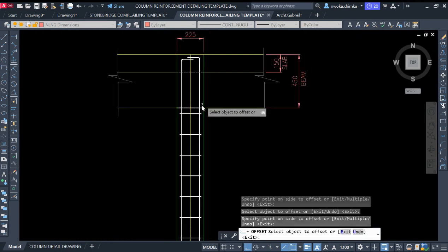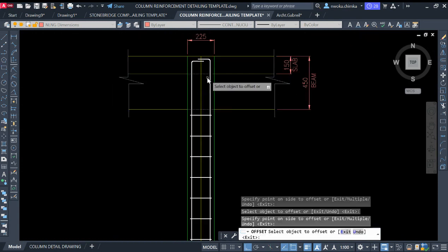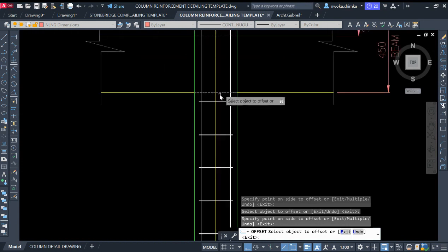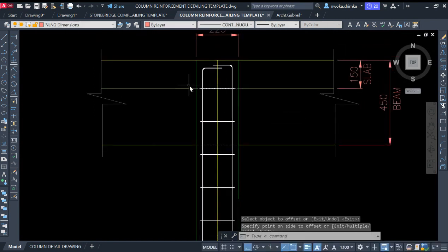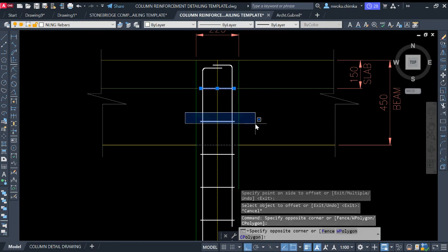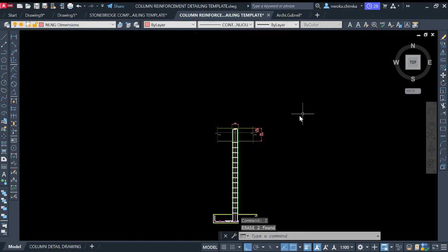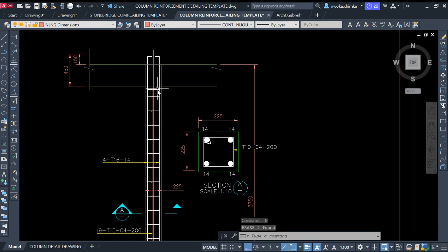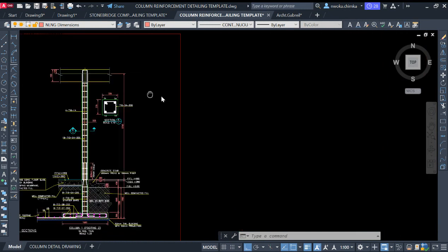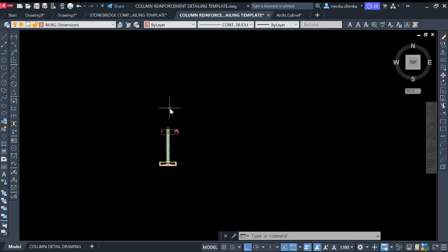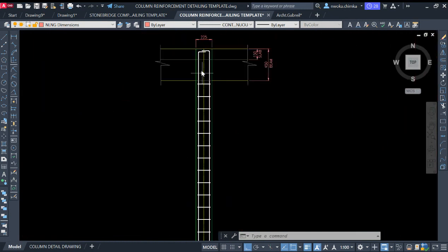So right now we just have to stop here because link reinforcement does not enter into the beam. The beam reinforcement we have to hold this column here. So we have to stop this directly at this point. You don't have to go into the beam to start showing the links in this place. This is wrong. So you just remove this and remove this and stop directly at the beam edge, as you can see it here. Also, if you look from our go by, our sample, the link stops directly on this point. So right now, what I'll do is show this link. So we have shown our reinforcement and also for the column.